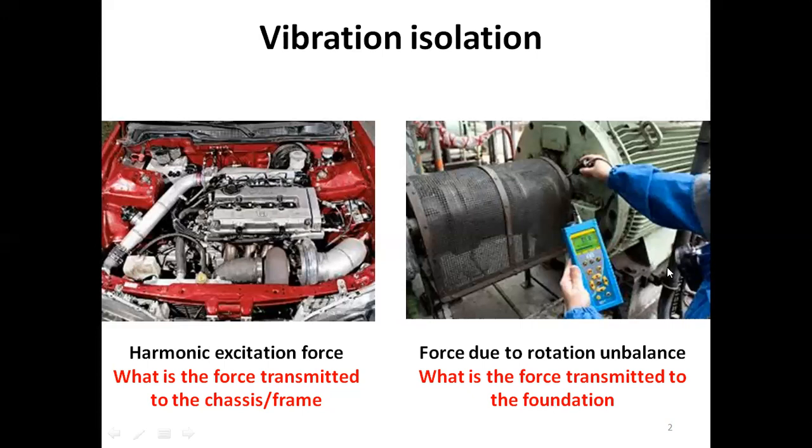We are interested in that because once we know the amount of force transmitted into the foundation or the chassis, and we come up with a mathematical model for that transmitted force, we would be in a position to simulate that force and further study how it behaves when we change the frequency of the excitation force, and how to reduce the effects of the transmitted force.